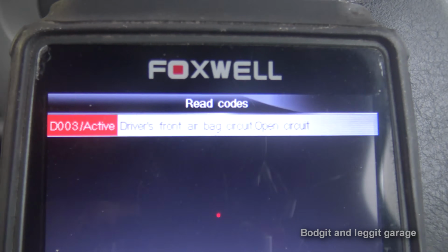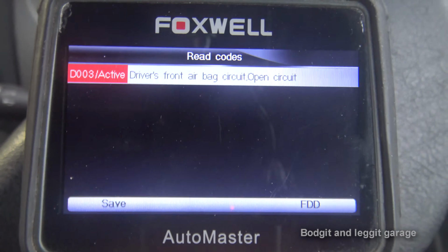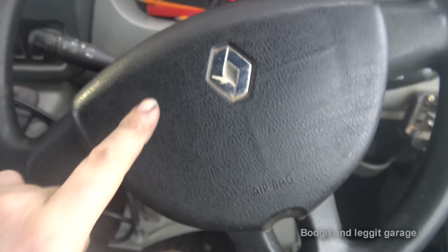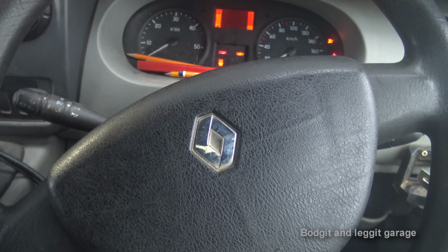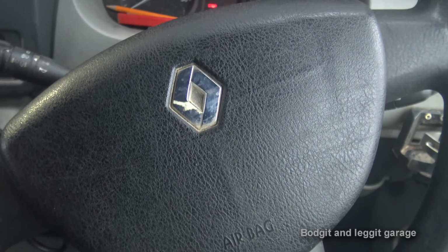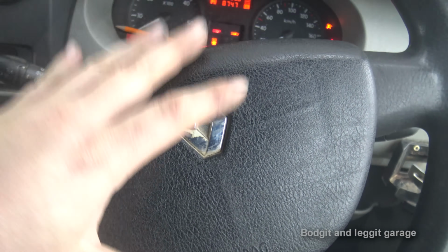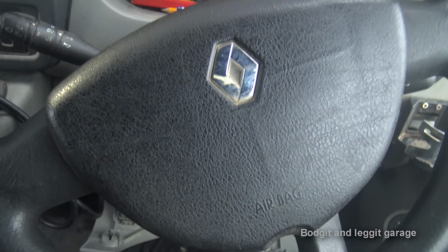Now, first thing you need to do is plug your scan tool in and see exactly what code you've got. As you can see, we've got a driver's airbag. Now, that could be a few things. That could be the airbag unit itself, it could be the clock spring, or it could be the wires going from the clock spring to the actual computer. So we need to eliminate exactly which one it is so we get the right part, because clock springs, airbags, stuff like that, they're very, very expensive and you don't want to be getting the wrong part.